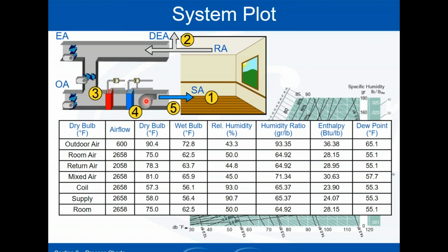If I don't, it's going to cause me to have a lower CFM, which then is going to affect the whole process. So if I have the filter in there that the system was designed around, then the filter pressure drop is not part of the discussion of the process. But if I swap the filter out and put in one with a higher pressure drop, it will have an effect on the overall process.